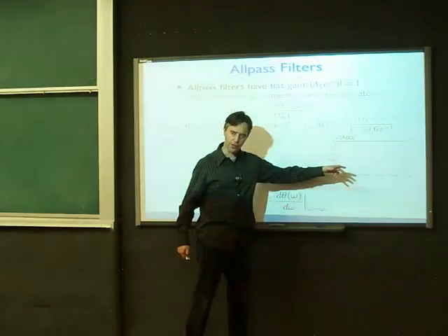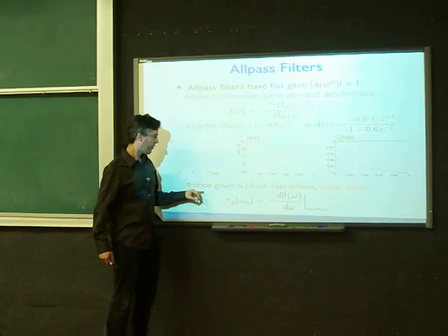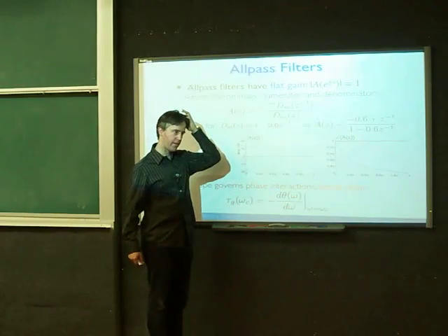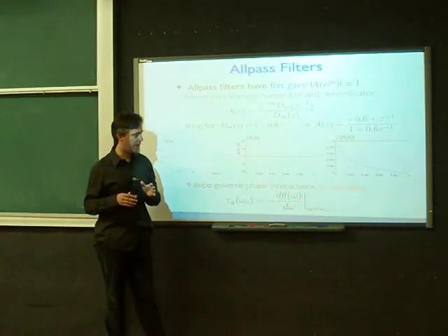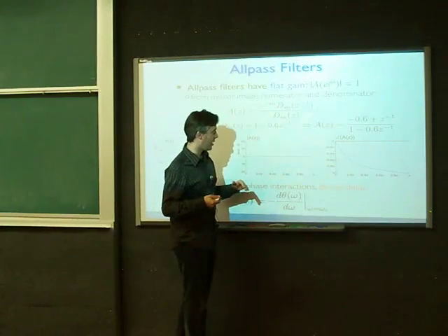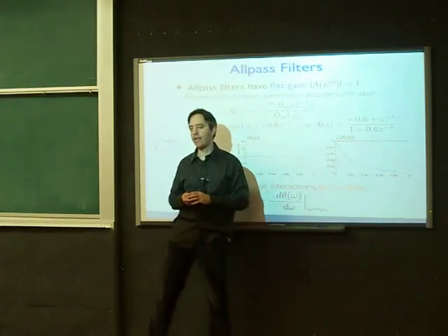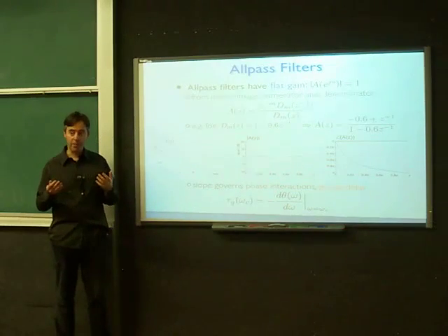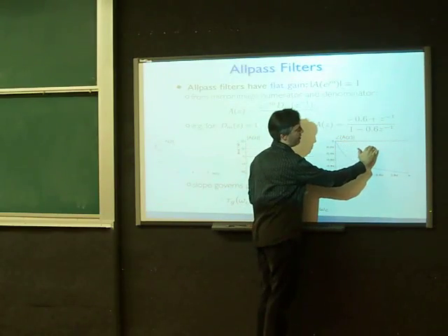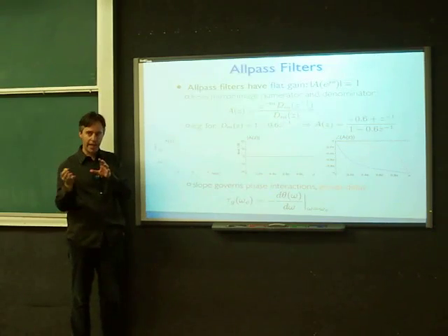Obviously, the absolute value of the phase is important in terms of achieving these phase cancellations. But there's also an important effect of the slope of the phase. It turns out that a pure delay signal is what we call a linear phase signal or a linear phase system in DSP, because it just has a phase function which is straight. But a phase function that curves like this is saying that the different frequencies are being delayed by different amounts, because the actual phase here is the delay, and so these are not on a straight line, so they're not having a constant delay with frequency. And so you have this effect of what happens when you delay the adjacent frequencies by different amounts.